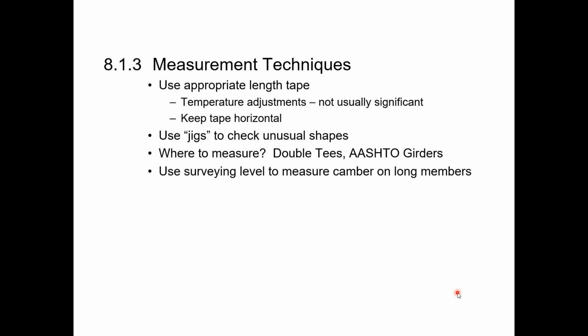There are some plants that make very complex, technically difficult pieces. I'm thinking specifically of things like tunnel liners. There are other products that are equally as complex, where not only are they radiused, but they're also radiused and sort of twisted. So you've got this two-way curvature going on that I wouldn't even say basically impossible. It would be impossible to measure accurately with a regular tape measure. And so there's different ways I've seen that be calculated and measured.